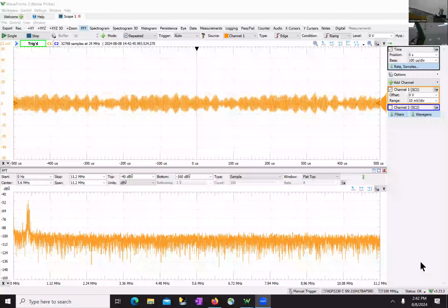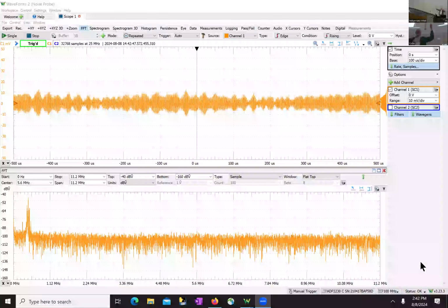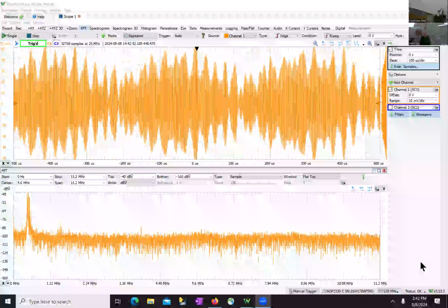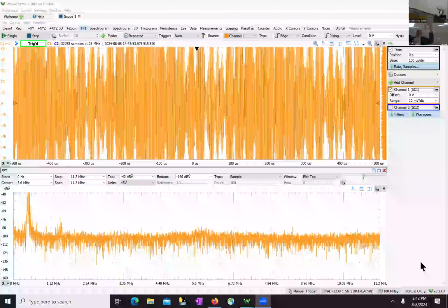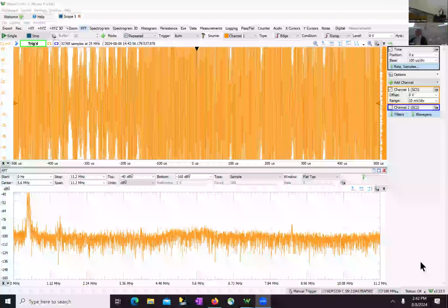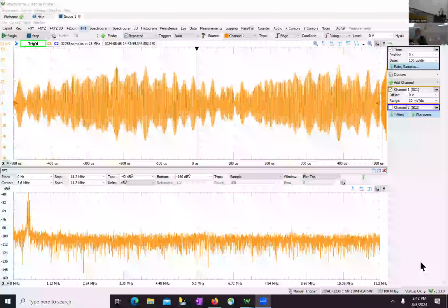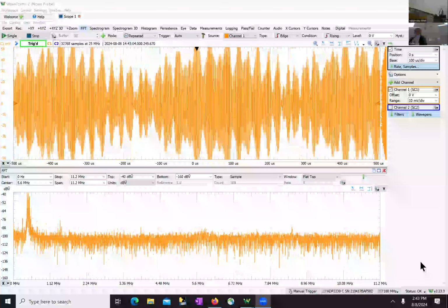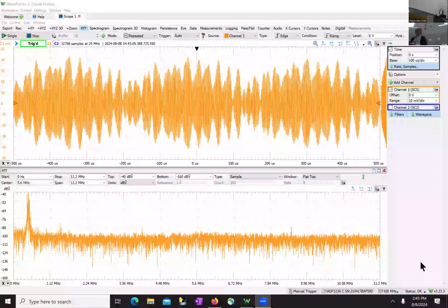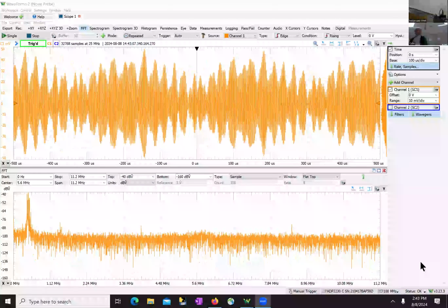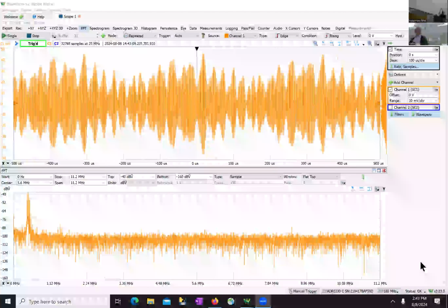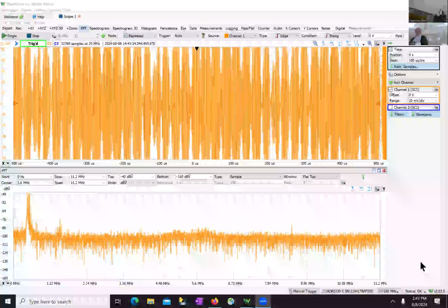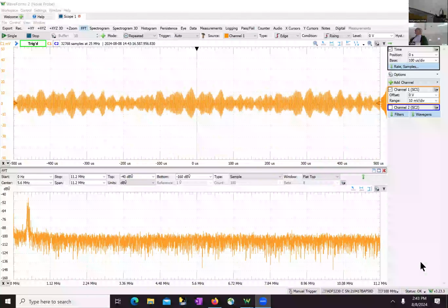And you notice that, right? Did you see that? Why is it doing that? I'm becoming part of the antenna. I have surface area here. The electromagnetic fields that are flowing through this room impinge upon my conductive body, and then I re-radiate it to the probe. So anyway, just some interesting pieces of information, an example of noise sources, where they come from, how you analyze them, and what you do with them. Any questions?